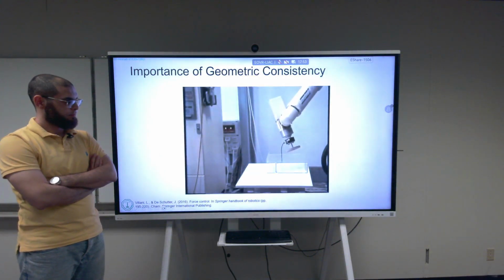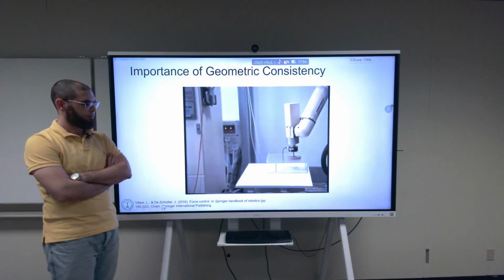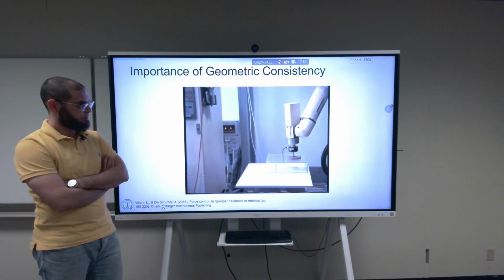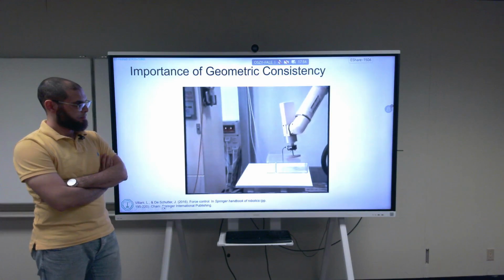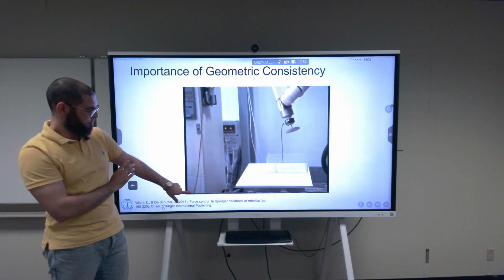The feature of impedance control can be best understood if a surface is placed in such a way as to obstruct the commanded path. When the end effector tool comes in contact with the surface, a compliant motion is obtained so as to accommodate the interaction force and moment.